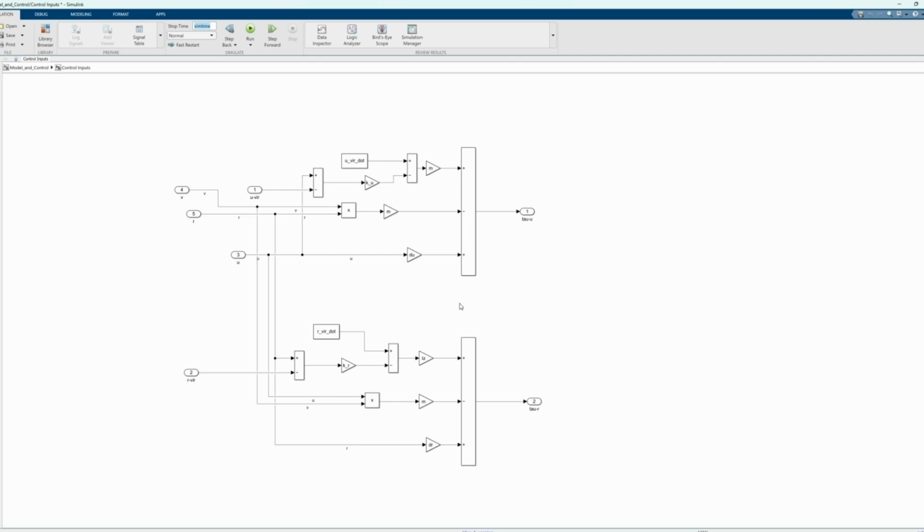You can extend this controller by designing a filter for this. Maybe you can design a Kalman filter, first order filter, or commanded filters, and then take the filtered output and give it at this pin. That will be a modified controller from this one. The basic concept will remain the same. You only have to change this block for that.